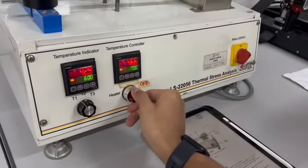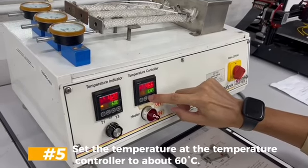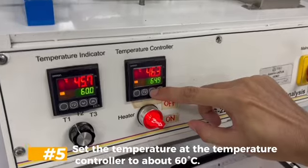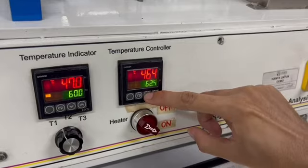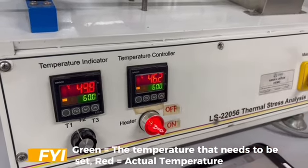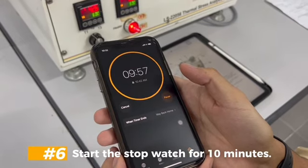Next, to start this experiment, we need to switch on the heater. The next step is to set the temperature at the temperature controller to about 60 degrees Celsius. For your information, the green color one is the temperature that we need to set, and the red color shows the actual temperature. Then, we need to start the stopwatch for about 10 minutes.